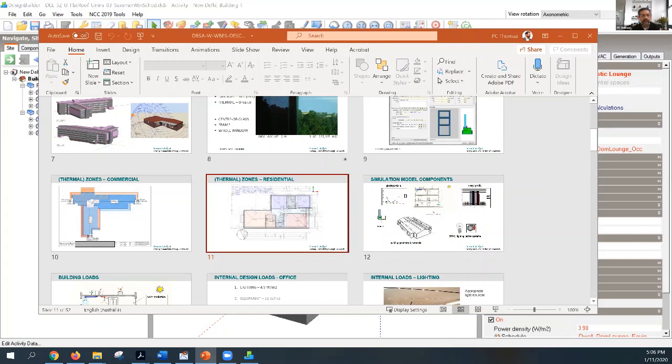Now, if you were able to devise a facade which completely blocked out the sun in summer and in winter didn't lose any heat, then you may have a building where there is no difference between any of the perimeters and the center zone. Go for it. But if you have significant differences between different perimeter areas and the center zones, you must have a zone. Well, you should have a zone. I know that people don't always do it, but yes.